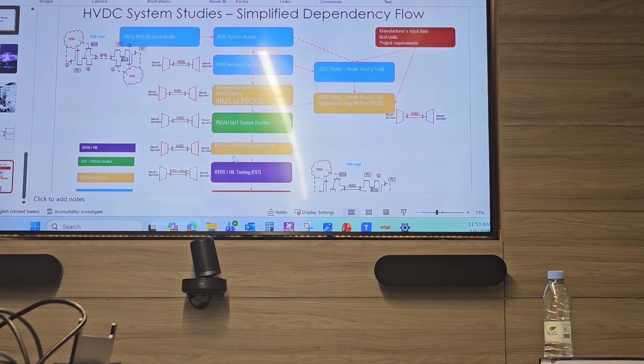This represents the Saudi network in terms of short circuits, voltage behavior, dynamic performance. So you simulate voltage, and for example, it will be the same behavior. They will simulate and inject these signals to the real equipment, because the same signals will be seen by these devices when we install them on site, because they come from CTs with the correct information. So it's not only simulation, it's really injecting those signals from CTs. It will not inject kiloamps, but it is reduced to CT level, so maybe secondary injection.